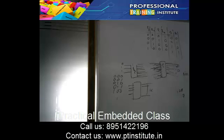See, consider I make this 4 lines, 2 outputs. Consider this is high. What output am I expecting? 1, 1. That is what I wrote. When this line is high, I am expecting 1, 1. When this line is high, I am expecting 0, 0, meaning both lines should go 0.